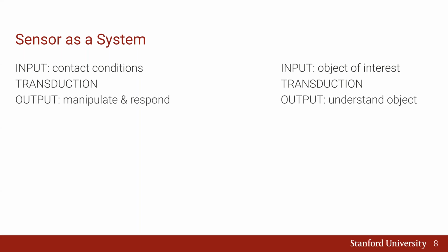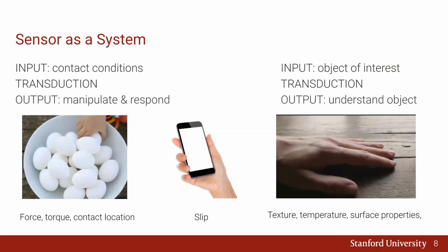The output of the tactile sensor can be thought of in terms of its applications. For robotic manipulation, the most common applications are for providing reactive context for events and for closing a control loop, such as in grasp stability assessments, or for also characterizing and identifying object properties, such as shape recognition.